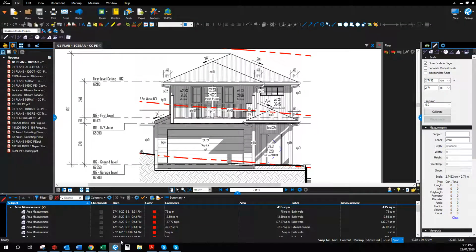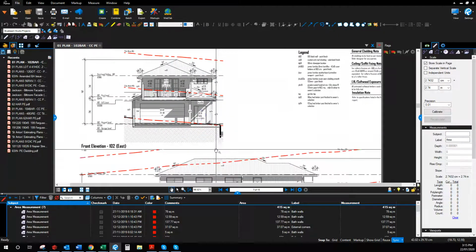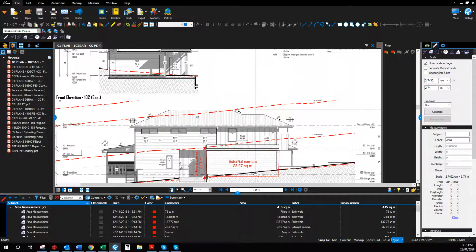Okay, so this is the cost center that we're going to be looking at, which is the eaves and cladding carpentry. So you can see on the plans here, this is your eaves all running around the house. We'll also be doing the underside of the front in the eave carpentry. And then you've obviously got all the cladding on the front of the house. So all lightweight cladding is done in this cost center. So where you've got block work shown here, we won't be doing, that's covered in a different cost center. So that's the block laying cost center.